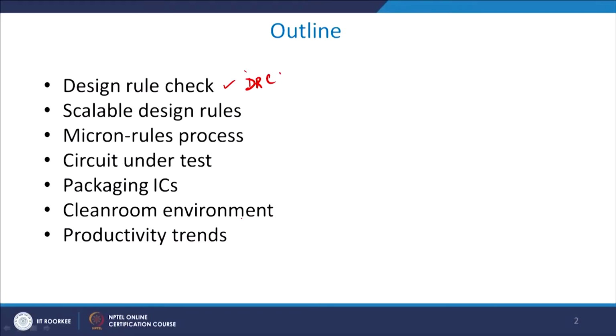So, you need to therefore do a checking of your design, and this is known as design rule check. Whatever design you have done on silicon using simulation platform tools, you need to do a thorough checking of that. Now, there are 2 types of rules: the first one is the lambda based design rule, the scalable design rule, and the second is the micron based design rule, which have been devised for quite a long time.